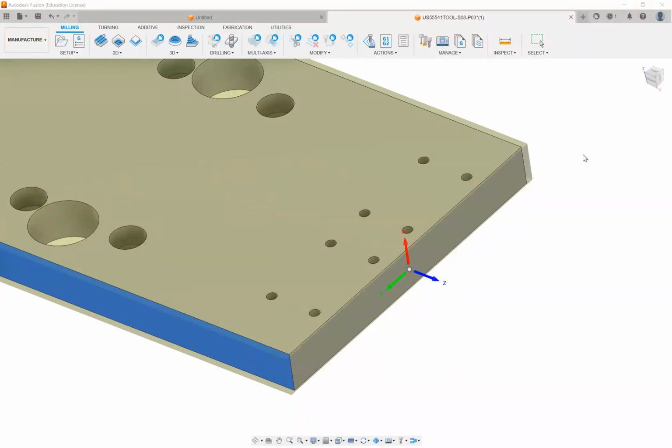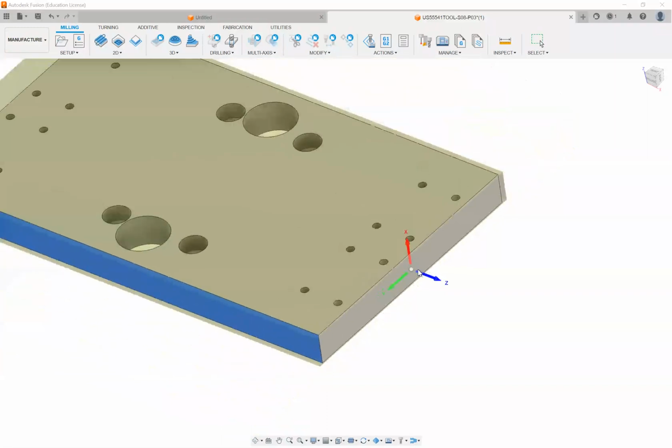As we talked about a minute ago, the Z has to go up away from the face of the part. The Y and the X basically should look like when we're drawing on the Cartesian coordinate system: the Y goes up, the X goes to the right. So if there's a problem with that, which is what we have here, we can go to Orientation and select Z axis plane and the X axis, and this will straighten it out for us.